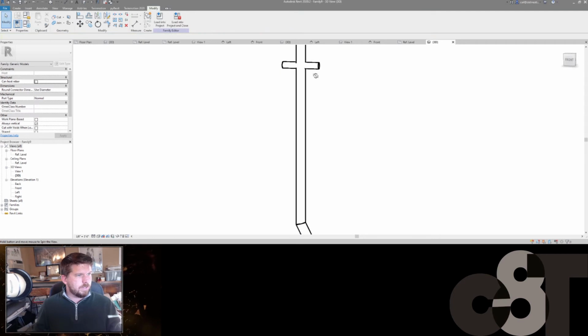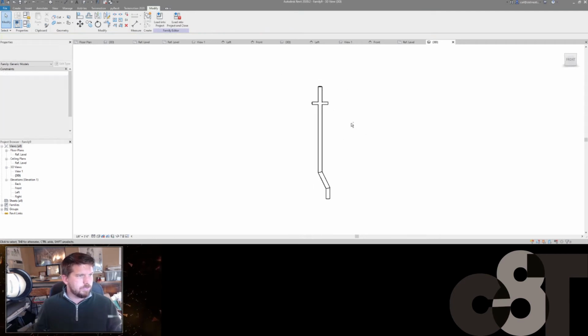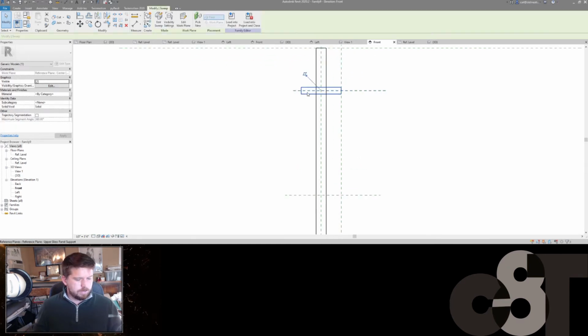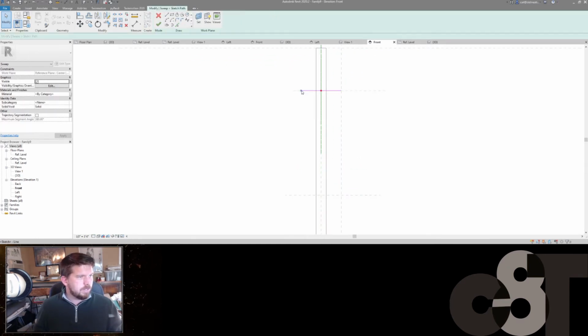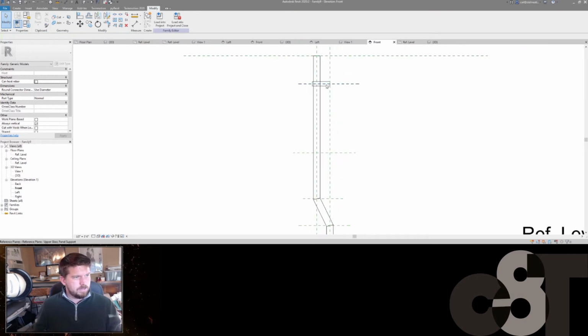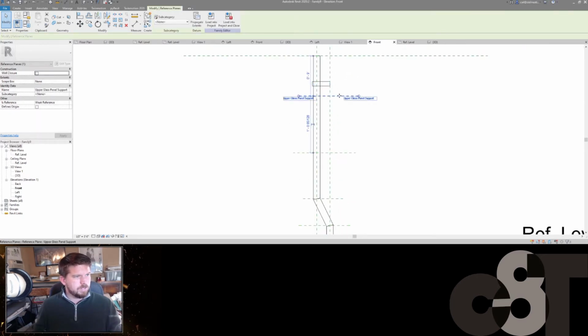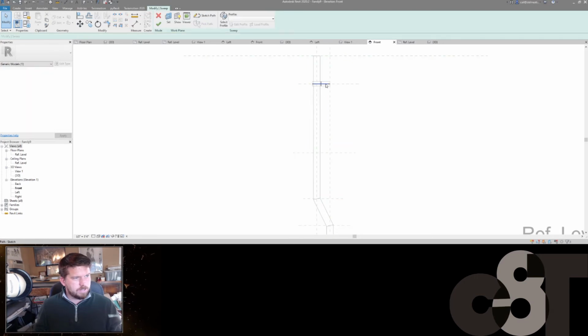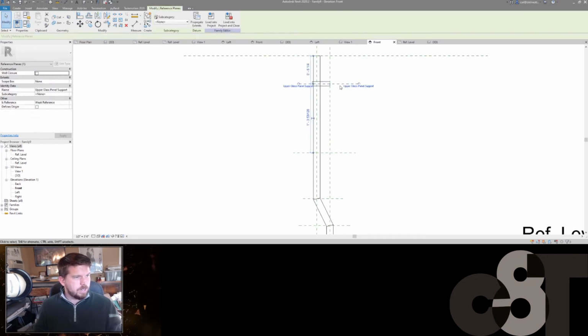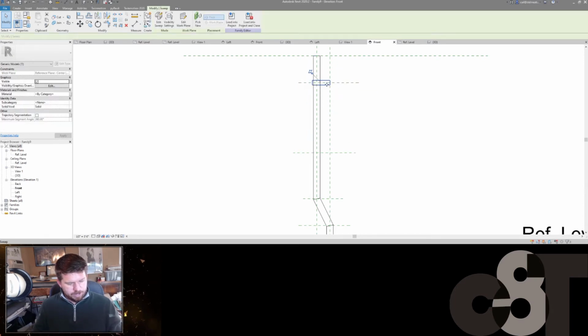All right, just like that. I feel like that's poking through just a little bit more than I was hoping. Yeah, so maybe this needs to be more like just 4 inches. Maybe that'll be just enough. Just like that. All right, so now what's going to happen is hopefully, nope, it's not. So I've got to go on align to lock the path here. So I'm just going to use align and lock that right there. And I'm going to finish that a couple times. Now, hopefully, when I move this up and down, we get a sweep that stays with that.